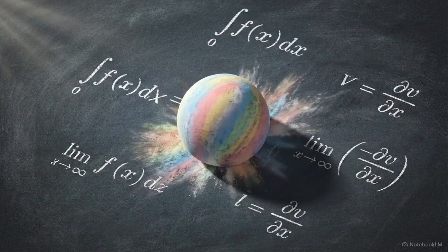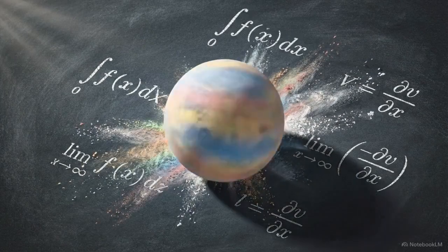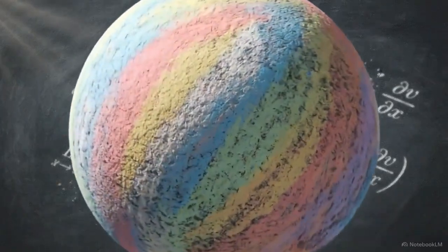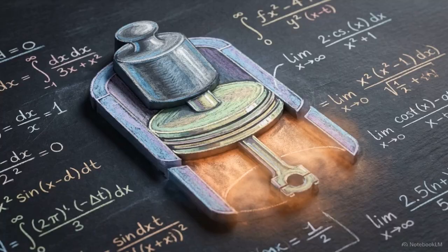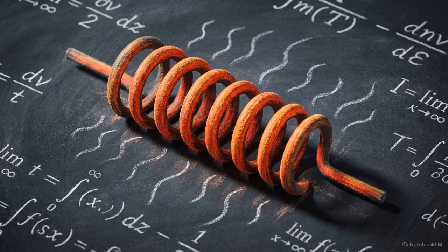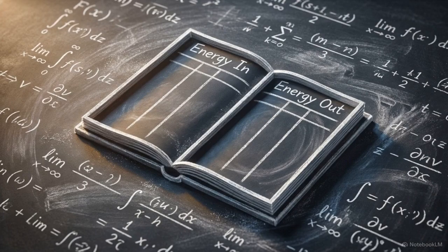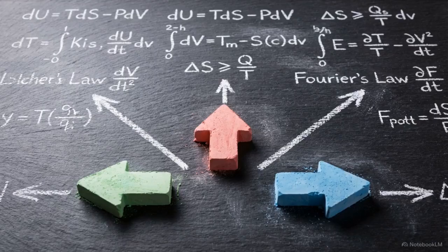Problems 1.8, 1.9, and 1.11 apply these concepts to physical systems, like bubbles in an explosive liquid or heating a water tank. Your job is to tally the energy inputs, sum the mechanical work, whether that's mass times gravity times height, or P delta V, and add it to the thermal energy from heat capacity or an electrical resistor. The first law of thermodynamics behaves like a conservation ledger. Once you define the process path, isothermal, isobaric, or adiabatic, the specific mathematical identity required to solve the energy balance becomes fixed.